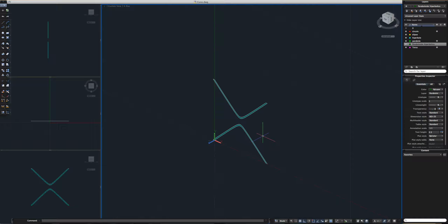And now, let's see, to save this, click UCS again, NA for name, let's save it as hyperbole UCS. You can use whatever name you want, I just thought that would be better for me. And now if you go back and you want to reposition your UCS in the alignment, all you need to do is do the UCS again, NA for name, and then instead of save, restore. Select the name, hyperbole UCS, and there you have it.